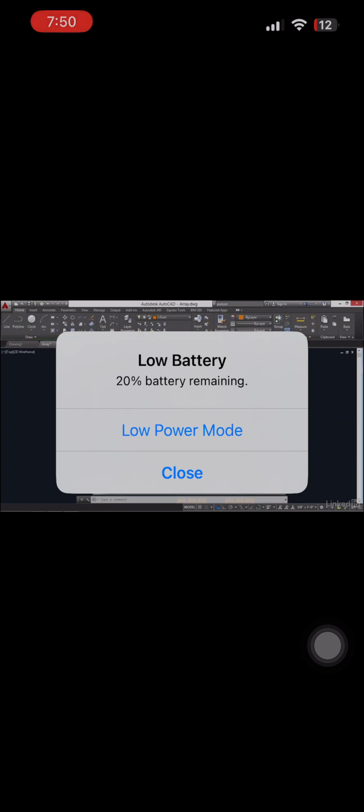Close the array. Another nice feature is because this is associated with the spline path, I can select the spline and alter its shape using the grips. And when I do that, all of the objects go along for the ride and they stay connected to that path.